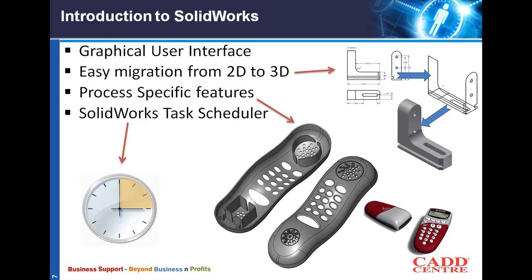So what you'll do here, you open a separate task scheduler application which comes with SolidWorks, and you will show the path where the files have to be converted. So these will be converted into the new version which you want. You don't require manual input. You can give a schedule time, starting at 9 o'clock and ending at 5 p.m. And also you can do some processes like printing the documents and creating drawings automatically by using templates, etc. You can do all this using SolidWorks Task Scheduler.